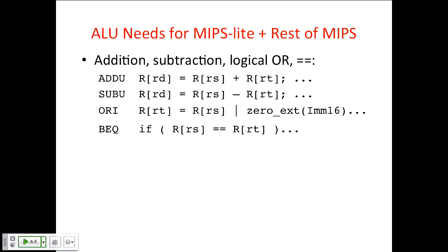You could use an XOR, but say you didn't have an XOR, how are you going to use an add/subtract to tell if 2 numbers are equal? Right, subtract them and then see if it's equal to 0. So you break it down: I can use the subtract unit to get a value that'll be 0 if they're equal. And now all I need is a unit that says if this 32-bit number is all zeros. And that's what we're going to do here.